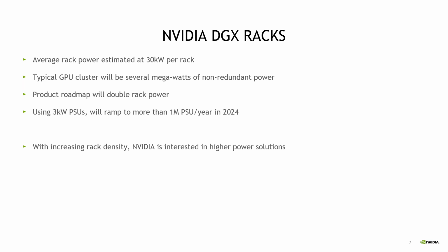Hey Dave, when you move to 660 amps for 35 kilowatts, does the shelf then go in the middle so that you're having to run 330 amps up and 330 amps down? Strictly speaking, as a power guy, yeah, that's what I want. The middle of the rack is also a very desirable position for all of the network, NVLink, high speed stuff.